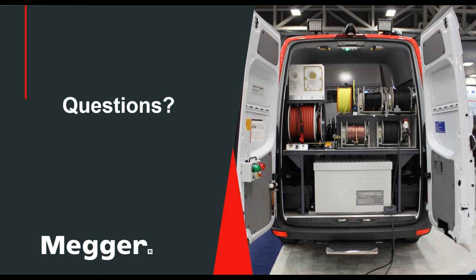Boy, I could tell war stories about this one. Yes, you can, but think it through. You have 2 faults, 2 paths to ground. When you start to apply high voltage, in general terms, that voltage is going to seek the path of least resistance to ground. So what happens when you have 2 faults, assuming that they have different resistances, is you'll find the lowest resistance fault first.